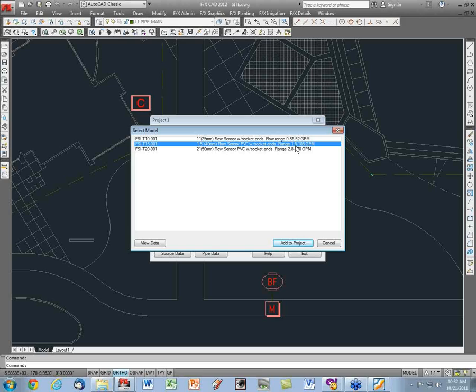And you go, oh my gosh, that's 1.5 inches on a 2.5 inch main line. That actually is very logical. We're only talking about a foot or two of pipe that is that smaller size. Your loss through there, as Norm pointed out, could be as little as what, 0.1 or 0.15 psi.